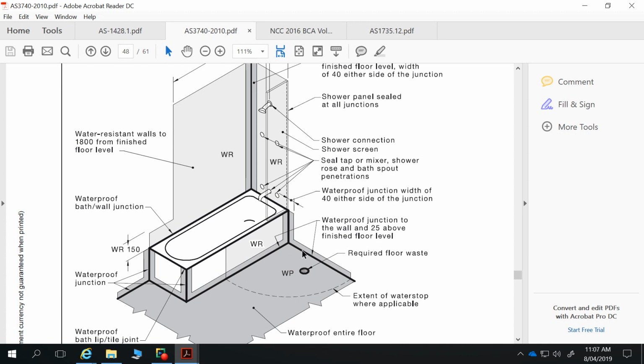The implications of that are that when you paint on this waterproofing membrane, you don't want to paint your walls over top of it because it is that thick plasticky type membrane. You're going to have this lumpy surface there. So that's why you see in your bathrooms, like for minimum tiling, still 150 millimeters of tiles going all the way around the edge of the bathroom, because you have to waterproof those junctions.